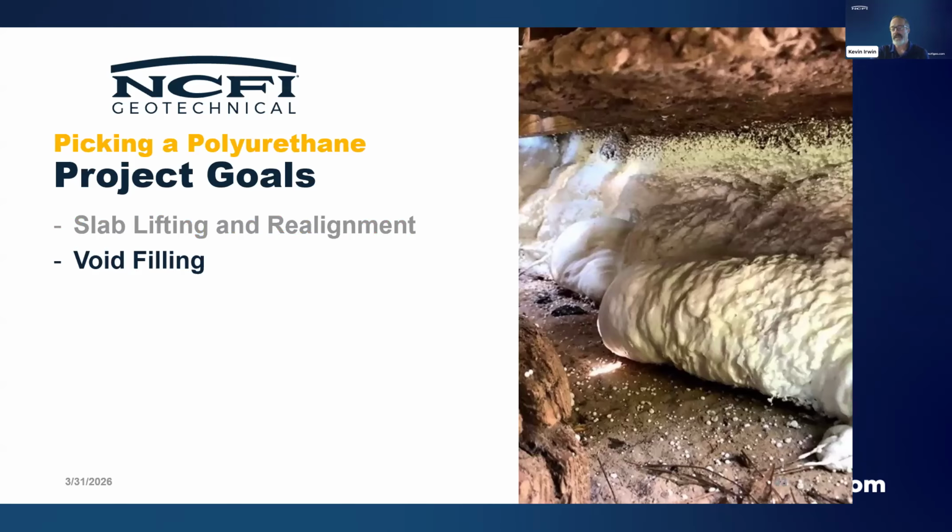Is this a void filling application, just like a pure void? In that case, if you need to put in thicker lifts, you can use one of our lower exotherm systems. There are 3 versions of those. They're all 2.2 pounds per cubic foot, but they vary in speed, hydrophobicity, and somewhat in density.